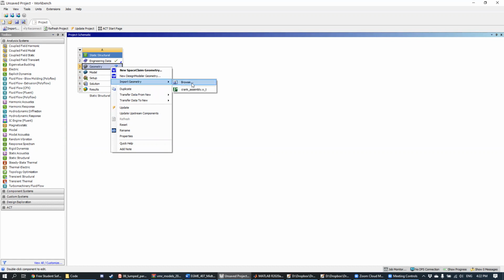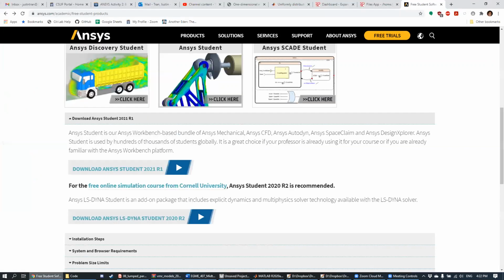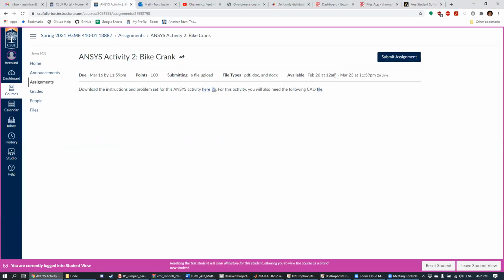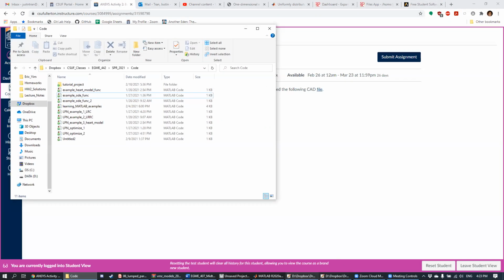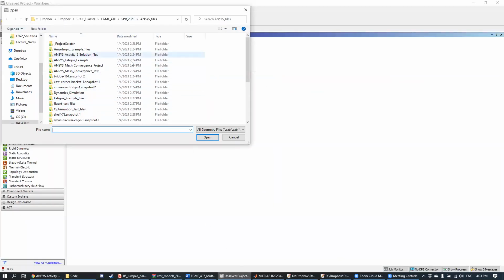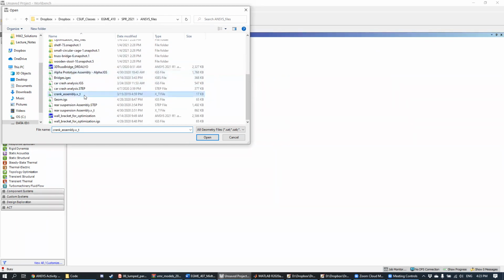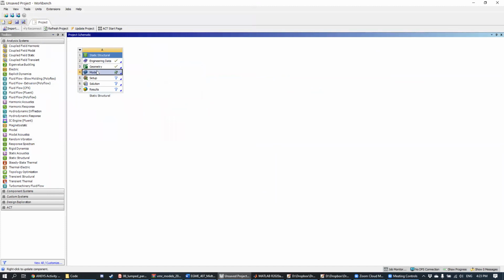Okay? And this will open up a file explorer on your computer where you can go find the files. At the beginning of class today, I asked you guys to download the CAD file from the Canvas site, right? If you download that file, you should see that it's called crank_assembly.x_t. Let's go ahead and find that file. For me, that file was in this folder because I was testing it earlier. But you're going to have to navigate to the location on your computer where you downloaded that file. Once you found it, you can just double click it, and that will load your geometry in just like that.